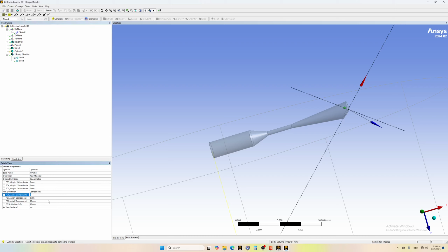So it will be let's say 6 millimeters about, and this is 0, and the radius we want. So the nozzle is about 2 millimeters diameter, so to have enough region outside to see the profile properly, let's say we will put 4. So the entire cylinder will be 8 millimeters. We'll see if it's too big.